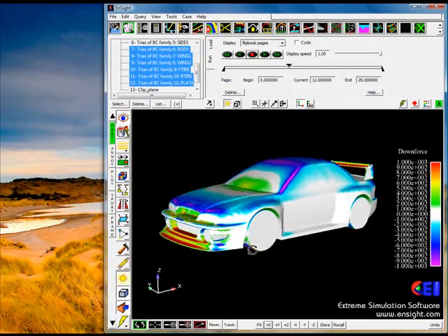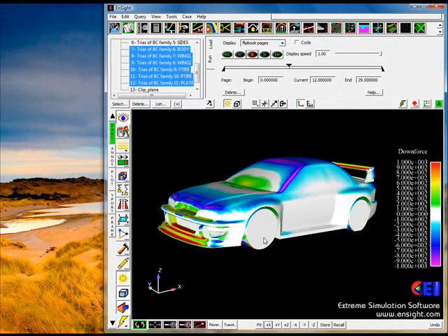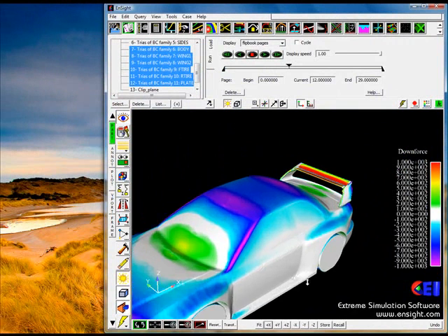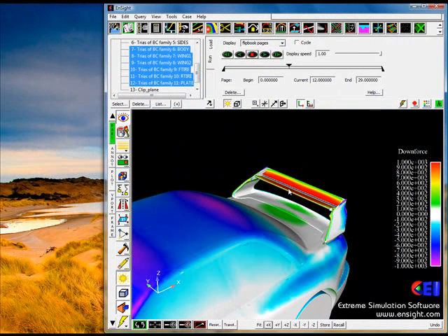What we'll do is now extend this a little bit, and we'll look at spanwise loading. For spanwise loading, we want to know how the load varies across this rear wing as we go from center to outboard. We've looked at the CP graph, but that only gives us sectional information. We'd like to integrate that over the surface, but we'd like to see it in a graph form where we have integrals at each station.